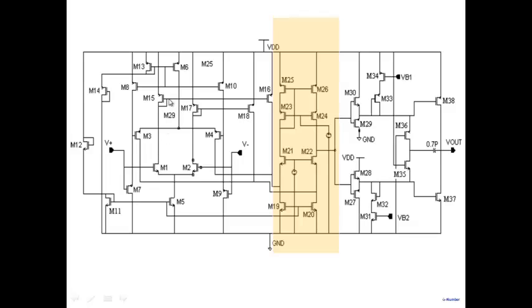M1, let's say M1 goes here, and then they have this PMOS, so it drives the current into it. Similarly, they have M2, it goes into M17, which helps in driving current into the load here. Remember, we said current going into the load, you have to convert it to current coming out of the load. So they're doing all of that using M15 and M16 now. And so this is a wide swing differential pair. This is a folded cascode load for it.